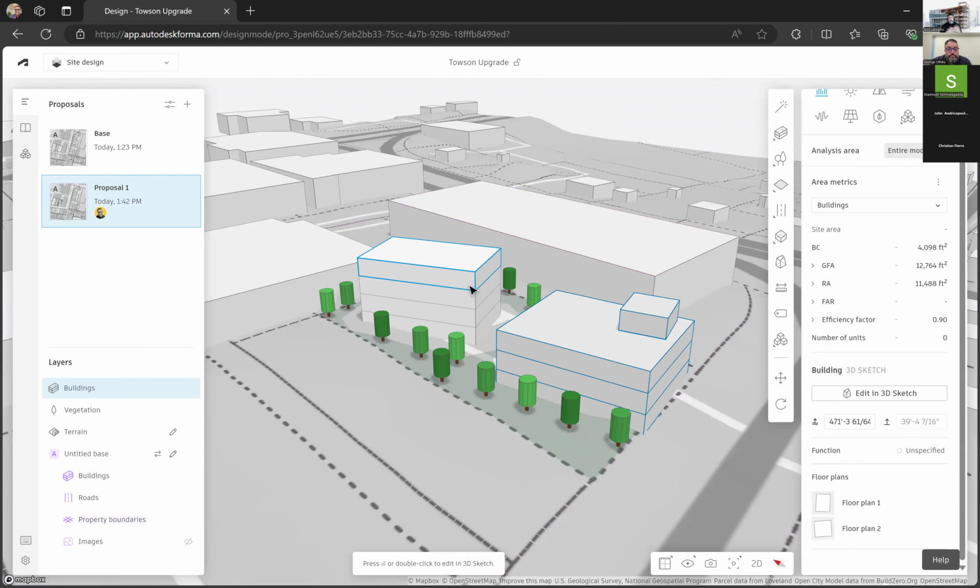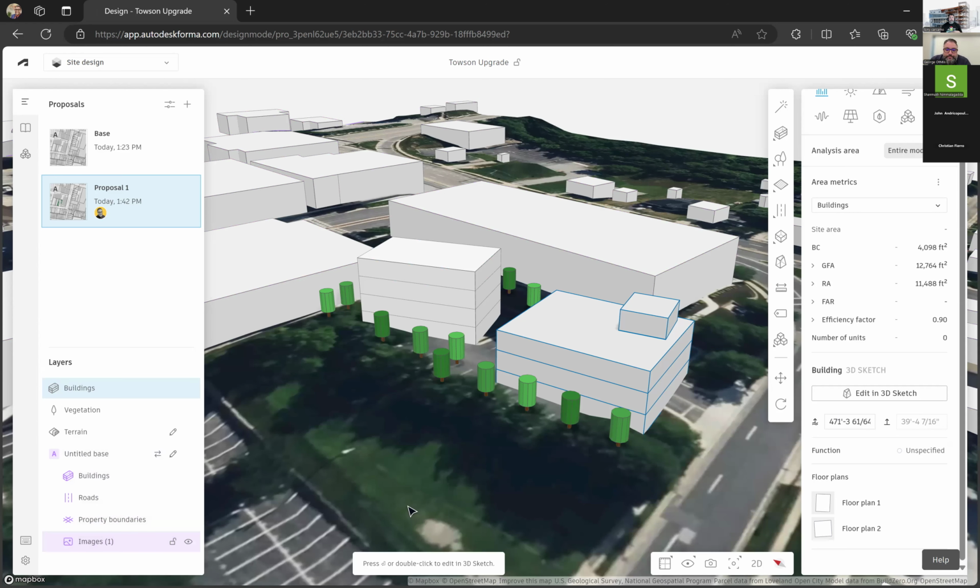But you can see the power. It's very similar to SketchUp and InfoWorks. It'd be interesting in 5 years if they don't just incorporate all the InfoWorks stuff in here or vice versa. You do the site modeling and then it's a push of a button and it puts it into InfoWorks and adds all the materials. Here you're not really applying materials, you're just creating generic conceptual plans, and the purpose is running analysis: look at the building, does it work? And then maybe push it into InfoWorks, which creates all the materials, and then push it back to Civil 3D, bringing in the roads, the parking, grading, and buildings.